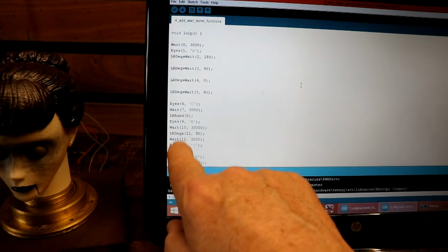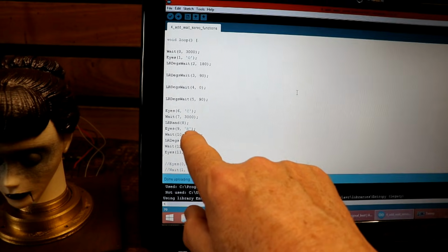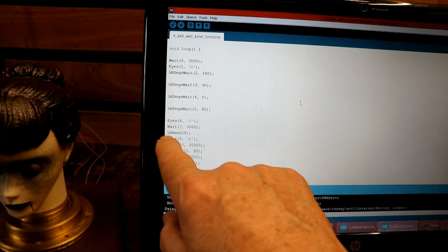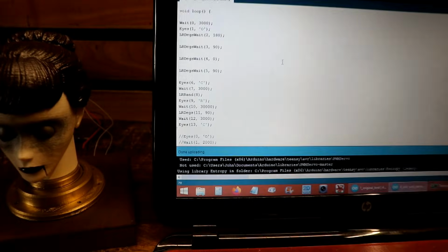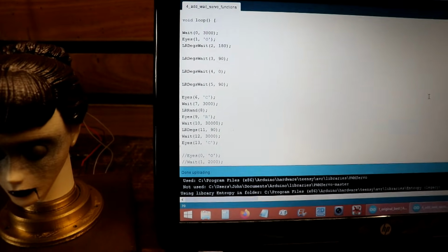Oh, there's so many things. Eyes right, eyes random, left, right random. So I've got all these functions, and it's been really difficult to write because they all use the millisecond timer, not millis, because Teensy, and apparently there's a library for the Arduino called elapsedMillis, which is really handy because it takes care of all the long, unsigned long numbers and the 49-day rollover when the Arduino runs out of room and goes back to zero, and it can catch you out. It takes care of all of that.